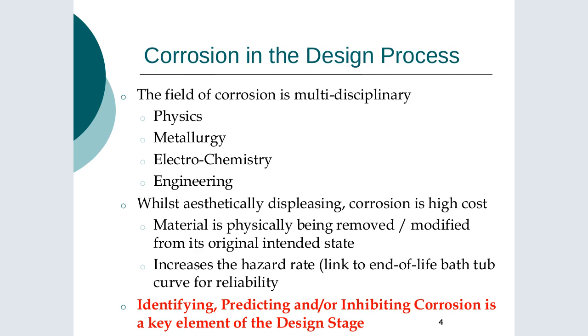If you take the example of the nuclear industry, when you're processing nuclear material, you don't really want the public to see lots of rusty pipes. Now, rusty pipes can be perfectly safe. I would say you can build a corrosion tolerance into your design, and you factor in the rate of attack. So it's not a concern. Things can look quite rusty, but actually be perfectly functioning and meeting the design requirements. And you've factored in the life of it, but someone just looking at it loses confidence in it.